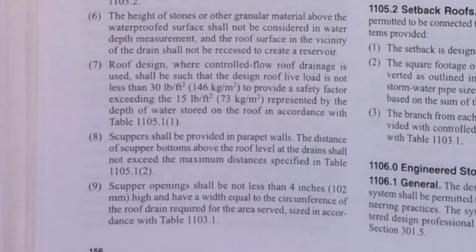Scuppers shall be provided in a parapet wall. The distance of the scupper bottom above the roof level at the drain shall not exceed the maximum distance specified in table 1105.12. The scupper openings shall be not less than 4 inches high, have a width equal to the circumference of the roof drain required for the area served, just like in